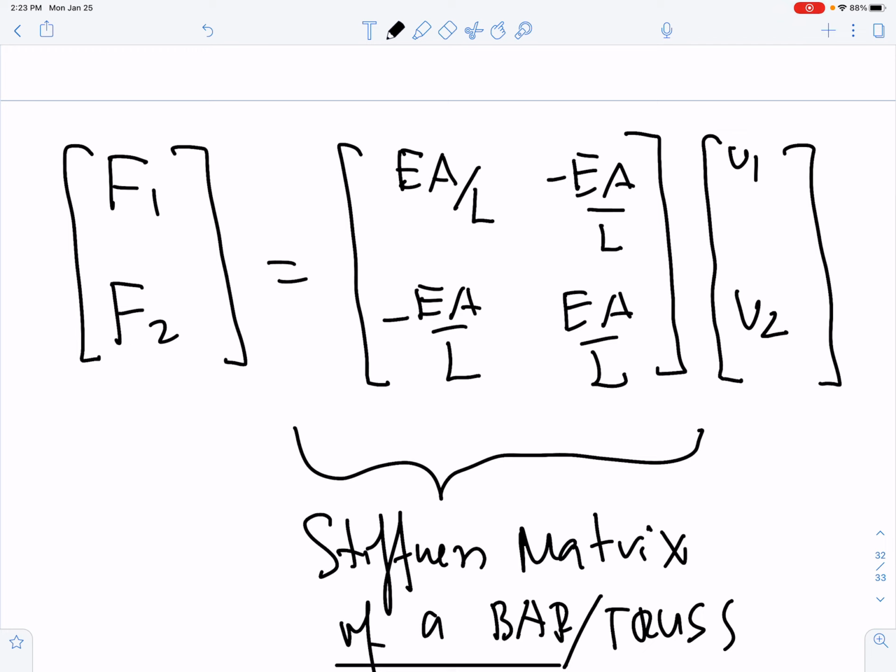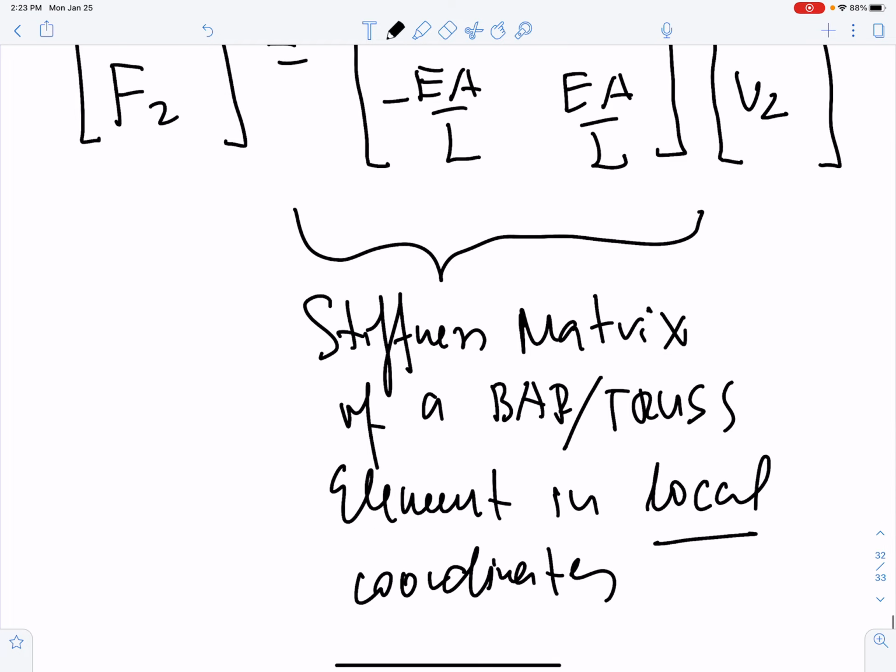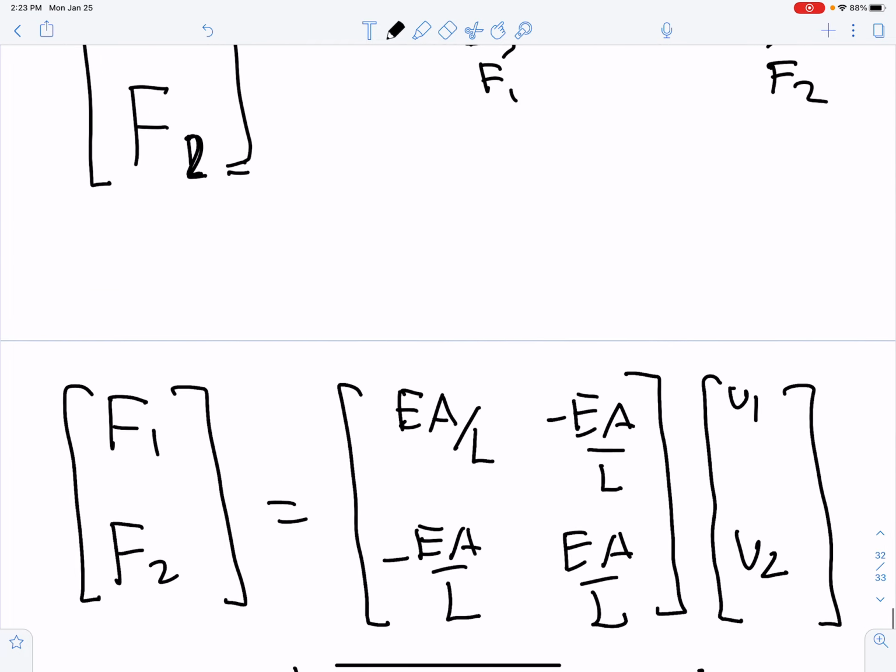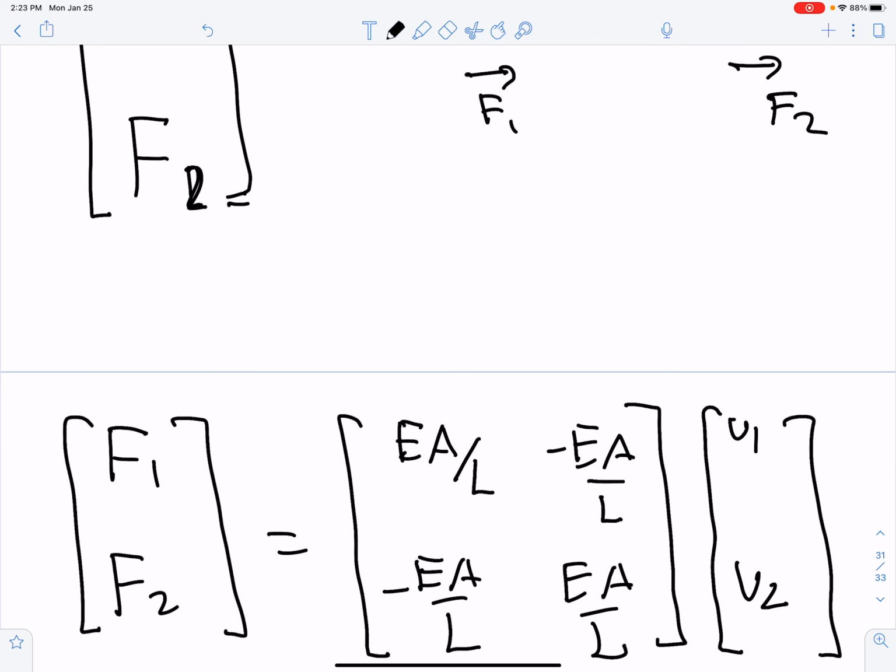As input, you take the displacements. As output, you get the forces. Because your displacement is two-dimensional in this case, your force vector is also two-dimensional, and the only general object that relates a two-dimensional vector with a two-dimensional vector in a linear fashion is a 2x2 matrix. That's the stiffness matrix. The way we derived it is we applied a unique and unit displacement.